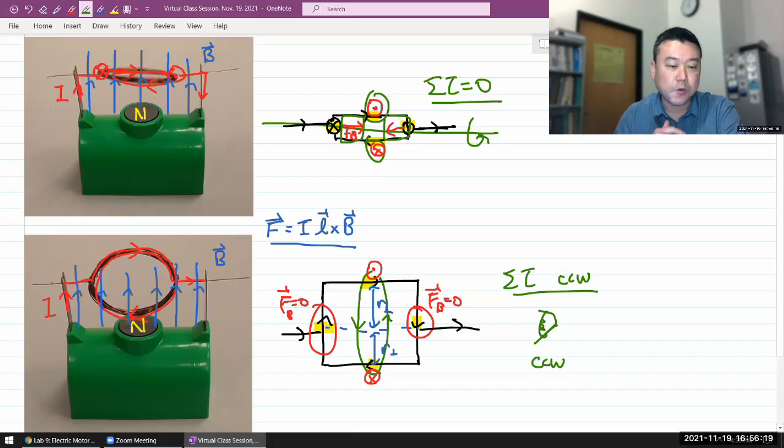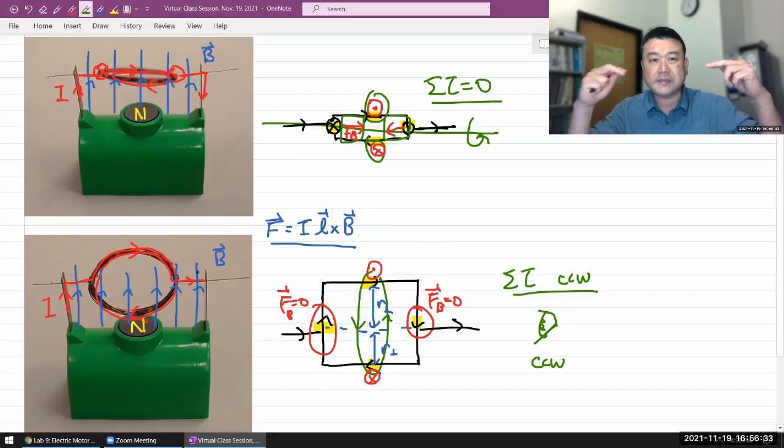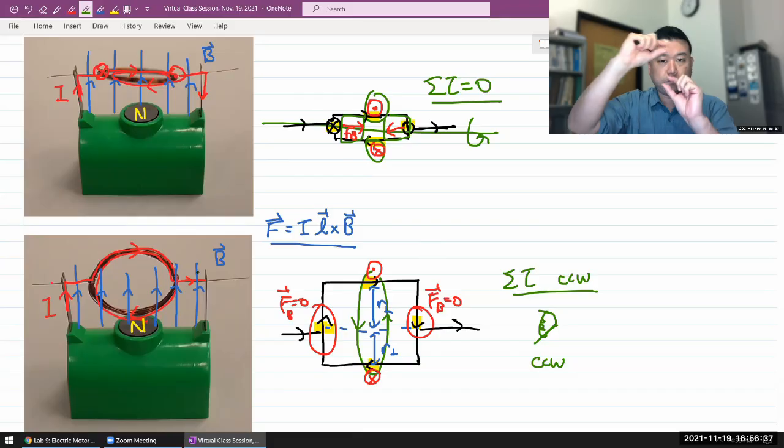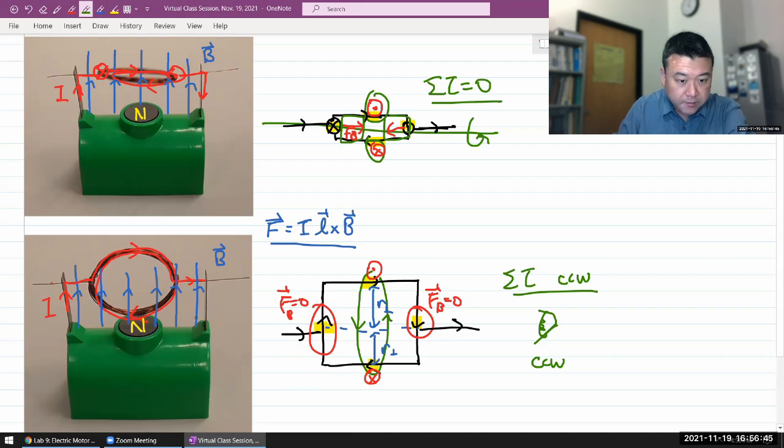And practically, how this demo works, the direction in which it spins, it would also depend. Wait, would it depend on? It does depend on which side of this straight wire is stripped, because I'm supposed to strip only one side. So when the whole loop is in one orientation versus the other, if I imagine flipping this around so that after it has turned 180 degrees, the current at the bottom is now flowing left to right, and the current at the top is flowing right to left, then you can see that the direction of torque will flip. That's why you need a bit of an asymmetry. In a practical motor, they have something called an alternator or commutator, something that will flip the direction of current as the motor turns so that the net torque is in a consistent direction.